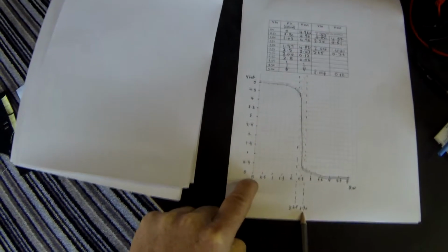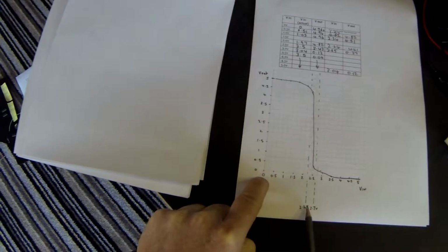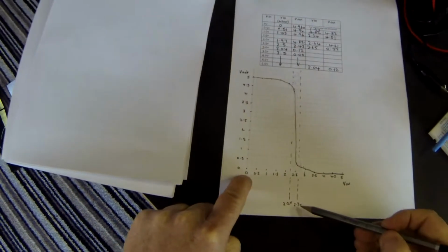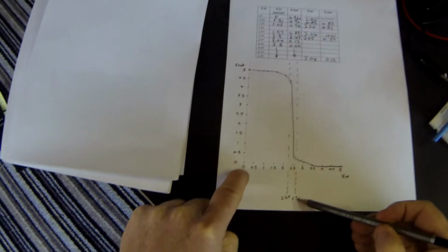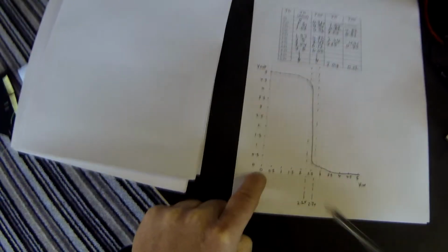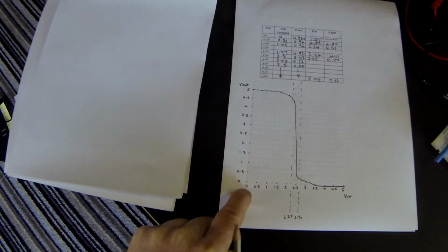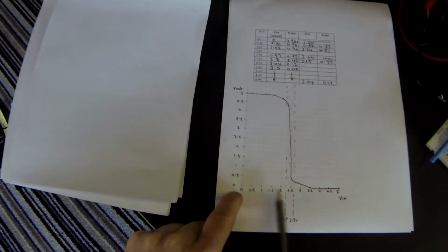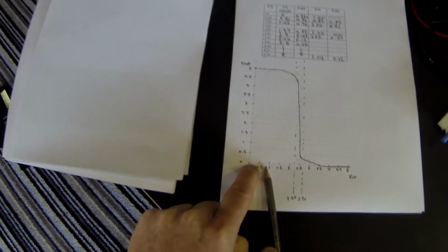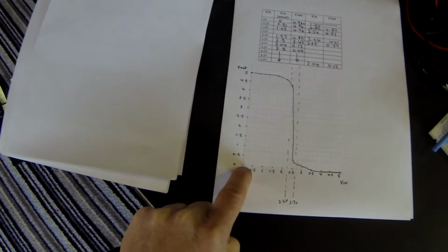So we can see from our NOT gate that anything below 2.2 is considered a high on V out, and anything above 2.7 volts is considered a low on V out. Arguably, you might want to look at it from the point of view as V in, that anything below 2.2 is considered a low, and anything above 2.7 is considered a high for V in.